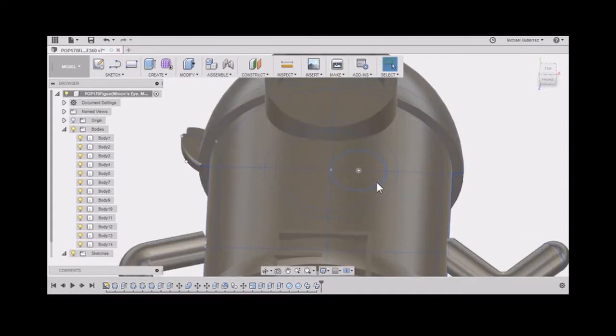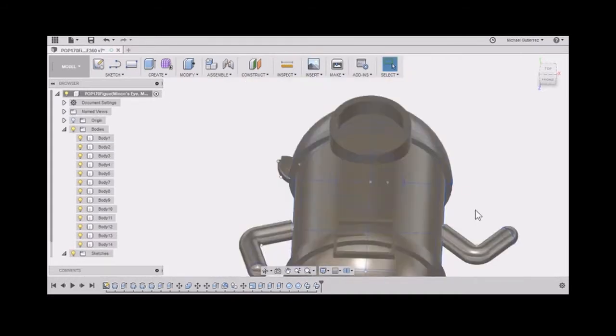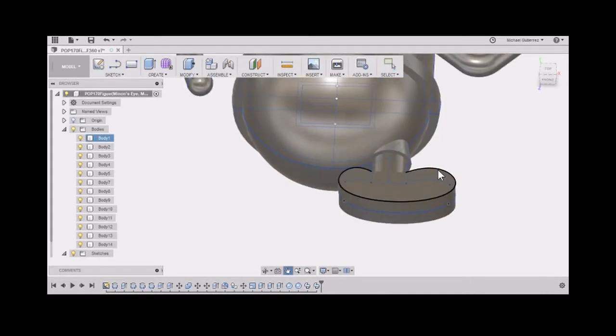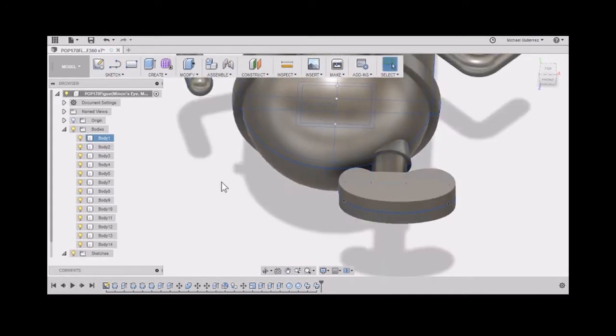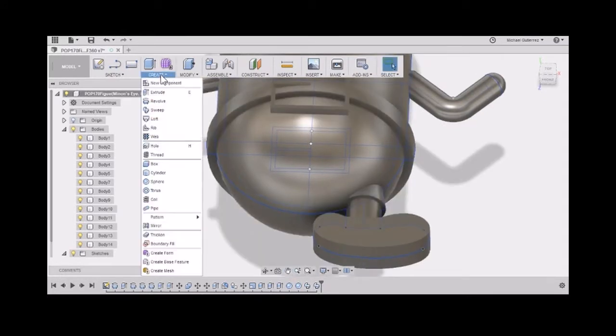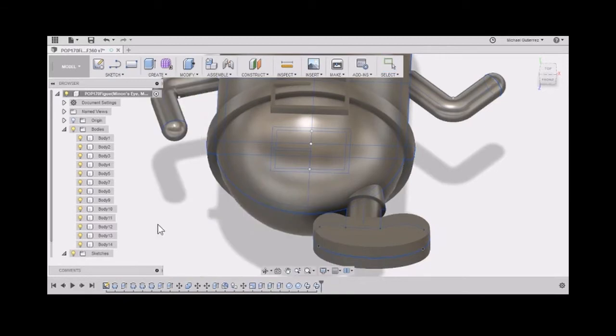Now we're going to do the eye. But before then, I'm going to tell you about this leg. It's only one leg. Obviously, there needs to be two legs. Instead of creating a whole sketch from here to here, or mirroring the sketch and repeating the process, we're going to mirror the body instead. So go to create, go to mirror. Now this was our first body. Here, click the body.